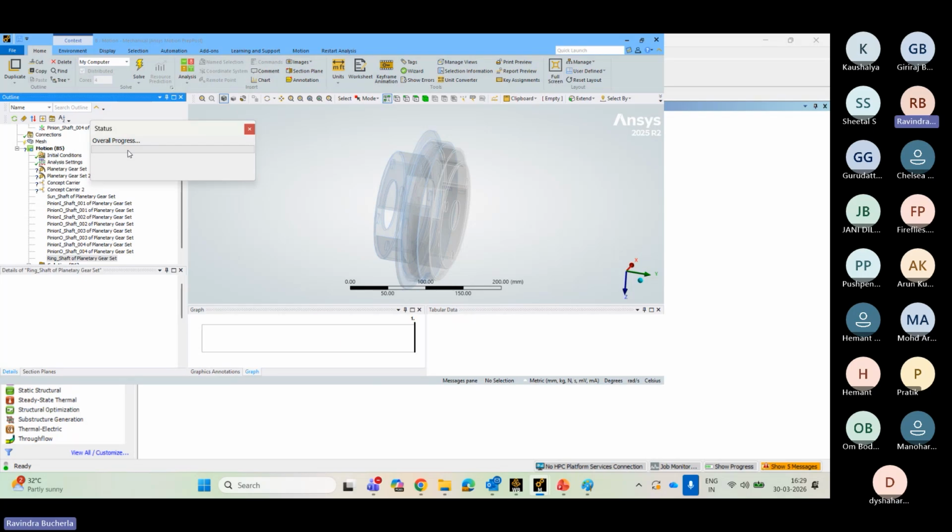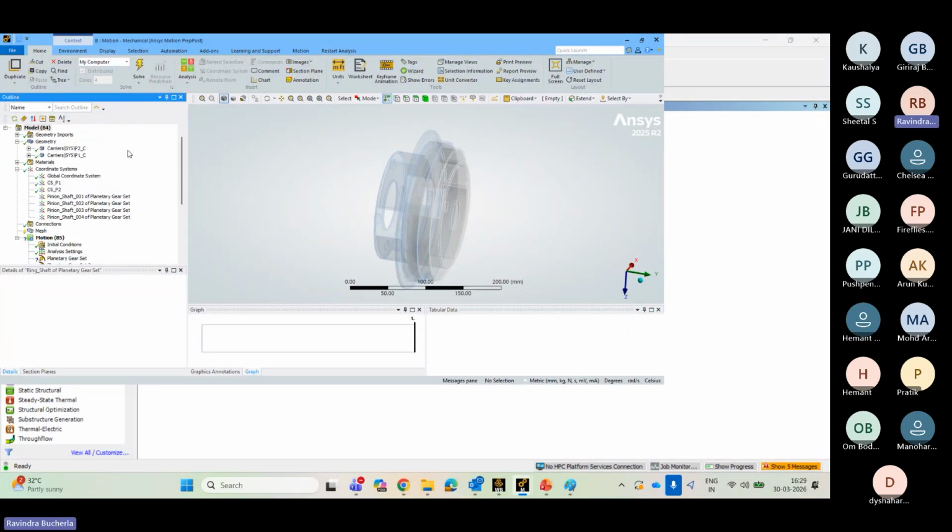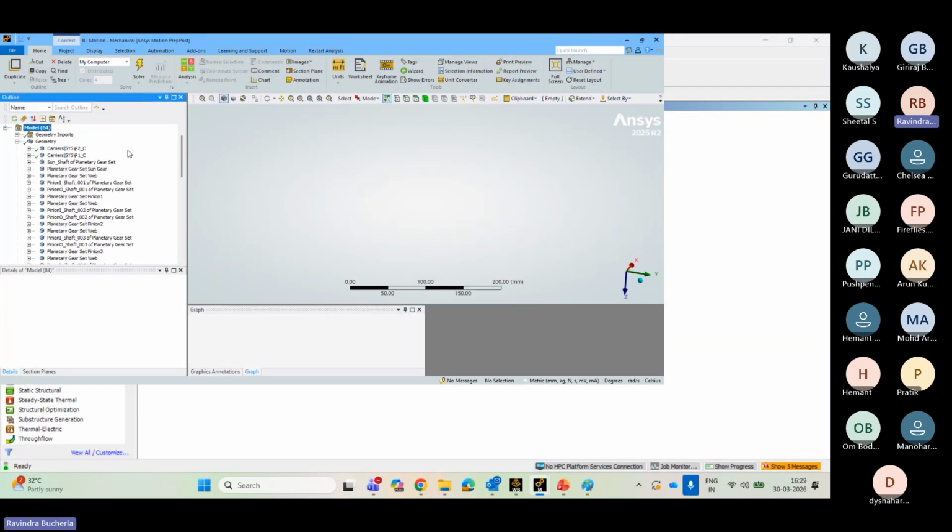This drivetrain toolkit will help us to create these kinds of gears. And once it creates the gears, it will generate the connections between them as well. So if we have this information, then usually we'll apply loads and boundary conditions as in the previous model.